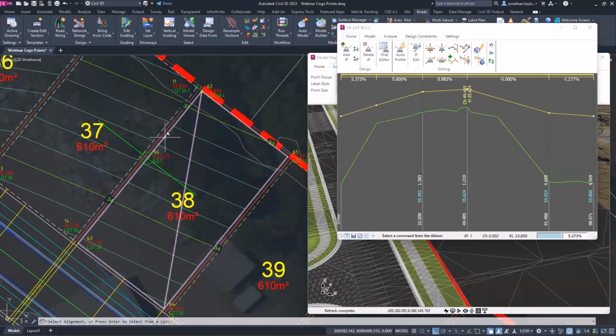You could actually reverse it by editing the polyline, adding a vertex where the point is, and then resample the whole thing and recompute, and then you probably get a sample point at that point, and then the triangulation would pick it up. But it's a bit of a round trip. It is. But yeah, that's the only way I can think of, Clinton, to actually do it.